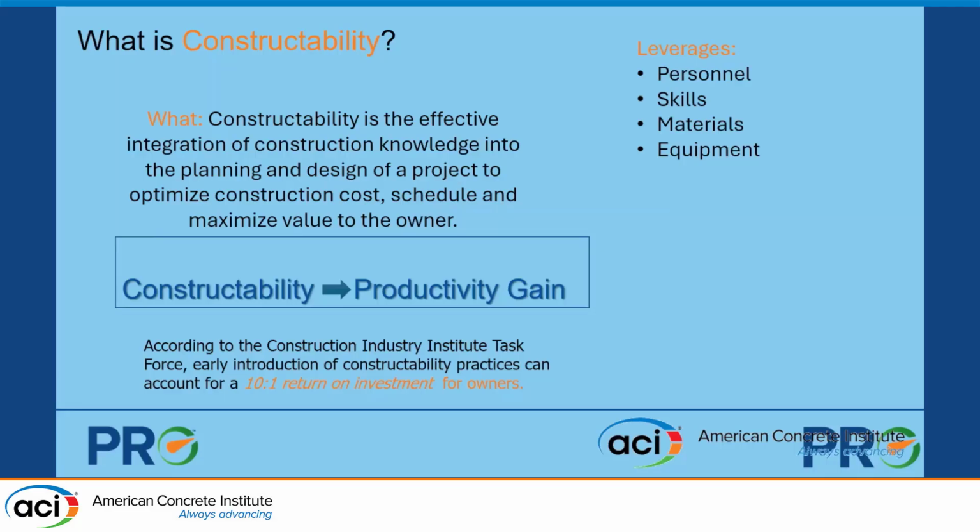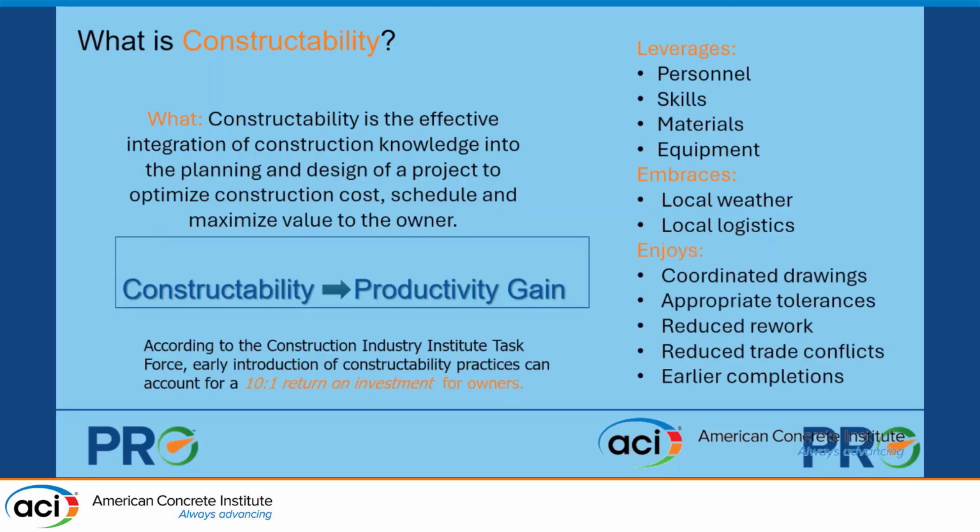Constructability allows the designer to leverage contractors' personnel, their skills, the materials, the equipment they use. It allows the design to embrace local weather or local logistics limitations. It offers the opportunity to have coordinated drawings, appropriate tolerances to build, reduced rework, reduced trade conflicts, and earlier completions. Boy, is that a powerful opportunity.